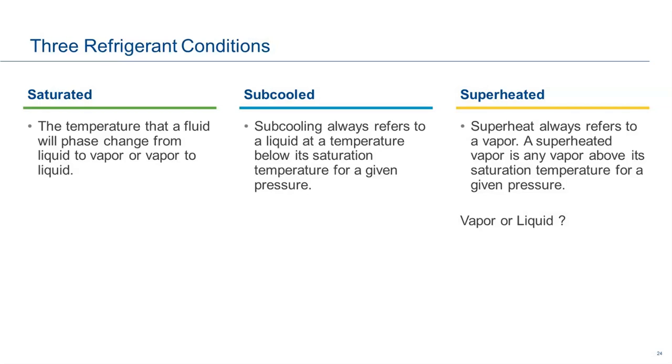It transfers heat better. And usually I get about a 50-50 split, and I always use an analogy that I learned from another instructor years ago. Think about it. If you could live outside with 60-degree temperature outside, could you survive for 24 hours? And the answer is yes. Could you survive in 60-degree water with it up to your neck, whether it's a swimming pool or a lake or whatever? And the answer is no, because it would remove the heat from your body so fast. Depending on your body mass, you might last minutes, you might last hours, but you wouldn't last 24 hours. So liquid is the answer of a better transfer, okay?